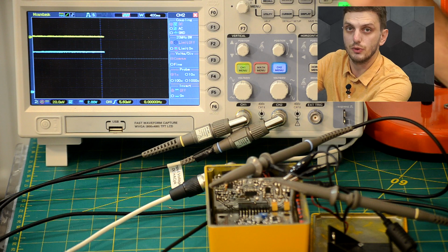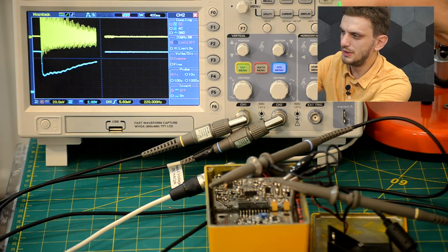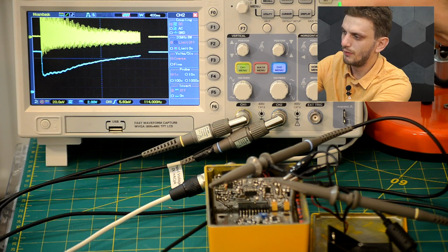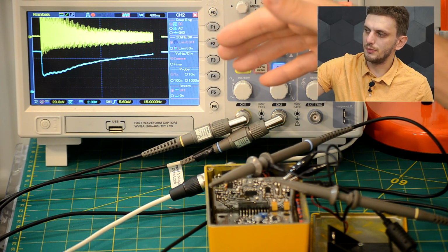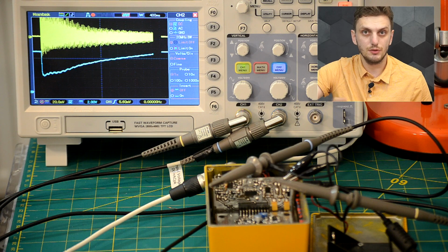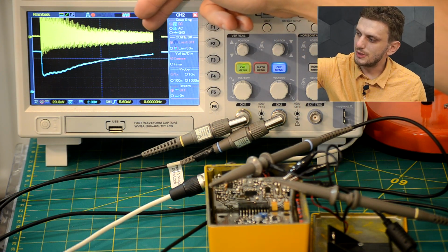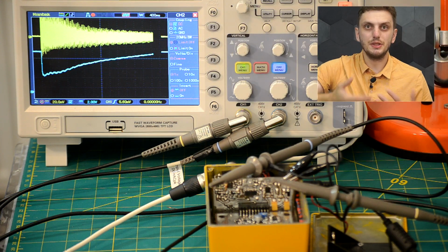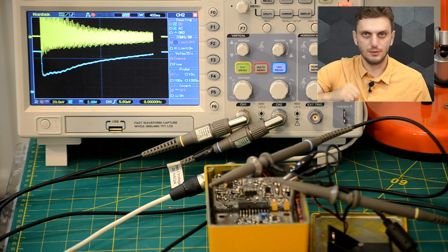But now when I strike one of the chords, we can see that our gain reduces, and then it slowly recovers as the input signal is decreasing. So when we have a very high input signal, we don't need that much gain, so the gain is being reduced by the circuit. But as the input signal reduces in amplitude, the gain increases back. So this way, the output amplitude is always kept constant.